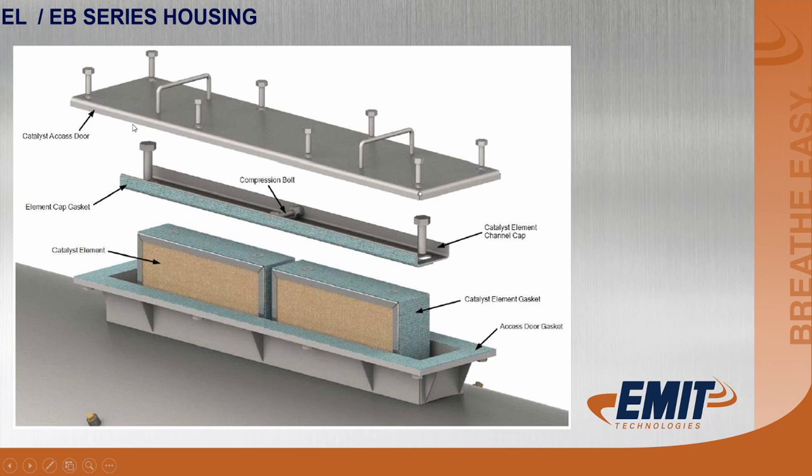And this is what the hardware looks like. You have the door. You have a channel cap, is what we call this piece right here. So this goes down, it's bolted on each end. And then you use a forcing screw to force it over against this bulkhead and seal it off. And then you finish tightening the bolts down once it's secured.